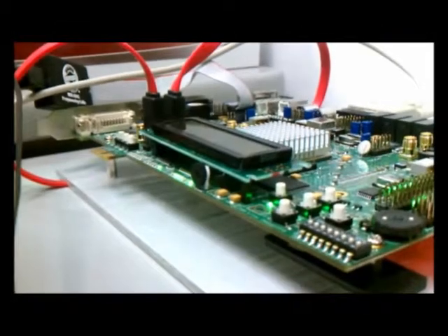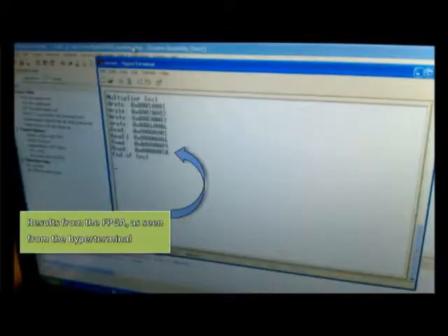We are going to show a small demonstration of a peripheral that the team created that multiplies 2 numbers and displays the output. To implement this peripheral, we made use of the read and write FIFO. We have to modify the code of the read and write FIFO to redirect the inputs to write the outputs into our multiplier peripheral, and read the output from the multiplier peripheral and send the results through the bus. This would then be displayed in our hyperterminal via the serial cable.